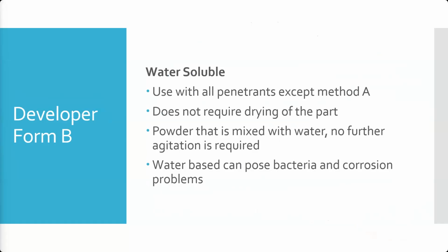So powder is mixed with water. It creates a solution. That means you don't have to continue to agitate it. Water-based, though, can pose things like bacteria. If it sits around long enough, it can start to grow stuff in it if it gets contaminated, and corrosion problems, moisture on your parts.